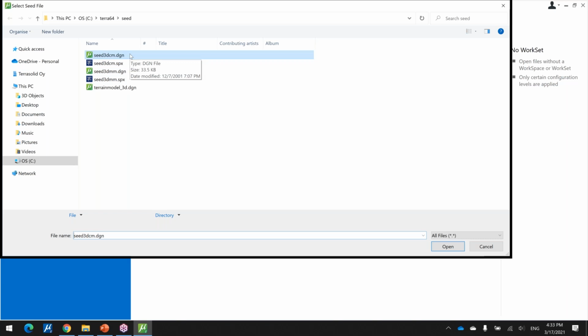It says the resolution which will be used for the coordinates. For airborne data, it is okay to use centimeter level. For mobile, you have better accuracy, so it makes sense to use millimeter level.